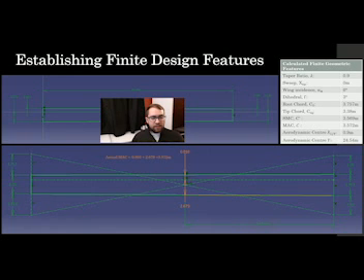Rapid manoeuvrability is not a priority here. The wings will be high mounted because high aspect ratio ailerons provide high roll force. Stability is the preferred priority. The aerodynamic centre and the mean aerodynamic chord were mathematically calculated and later confirmed for accuracy using projected methods as shown in the lower CATIA sketch here.